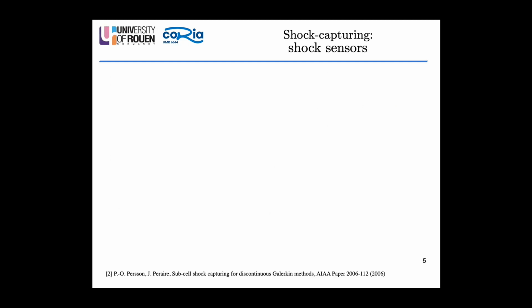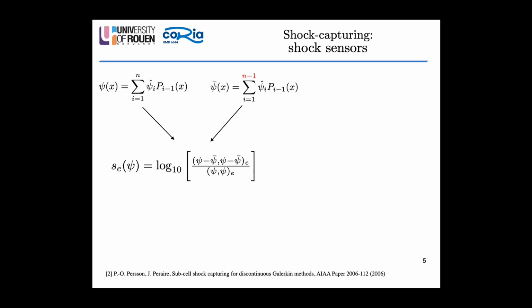In both cases, whether you use limiters or artificial viscosities, you always have to distinguish two separate steps. The first is shock detection, essentially to identify sharp features, and the second is shock regularization. Within the high-order framework, you can use the full polynomial expansion of a given signal and the truncated series to compute a scalar quantity which quantifies the level of regularity of the signal within the finite element, essentially comparing the L2 energy associated with only the highest mode with that of the whole expansion.